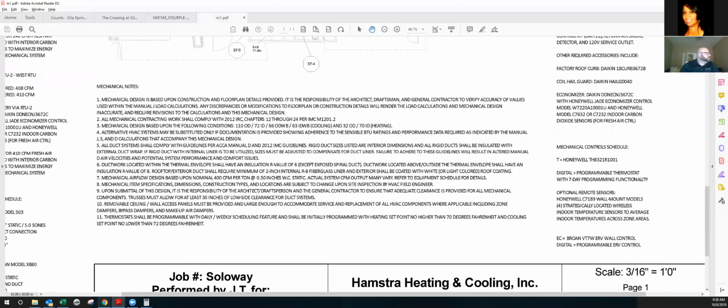That was just an example I wanted to use to show how you can look for that information. Now, in some scenarios, it will not be anywhere on the drawings. In that case, we would use the standard AHRI conditions that we talked about, the 95, 80, 67, and then we would qualify and say expanded cooling per AHRI standard.